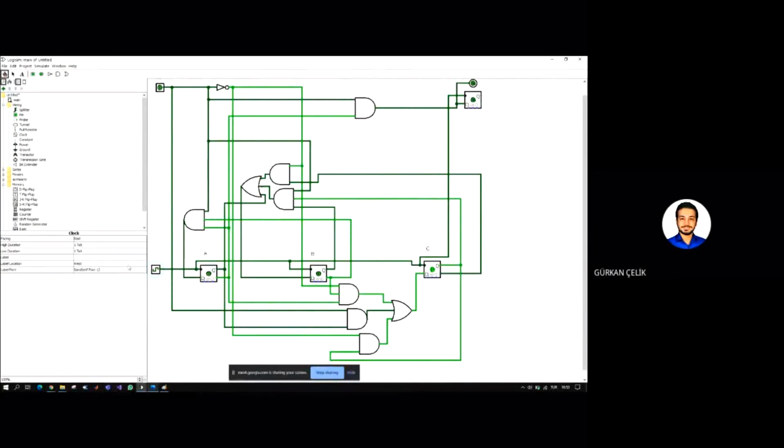Okay. And if we have input 0 and the state is 0, 0, 1, it should stay the same for the next state, right? 0, 0, 1 again. Let me try this. Oh, nothing changes. Good, right? Any question? No. What if we change the input to 1 and we have 0, 0, 1? 1 second. 1, 0, 0. True. And output is 1. You understand? Yes. And output should be 1.